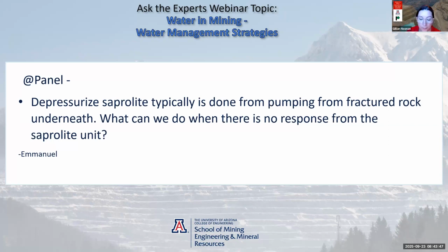I was just going to add that, in addition to that, it's about understanding your system. There may be something else causing that. It may appear there's no response, and it could be because there's some external recharge source entering that saprolite unit, such as a large waste rock dump on the edge of your pit, or a perimeter drain that allows infiltration into it. So just be sure you understand your system and pick the correct response accordingly. Very good point.